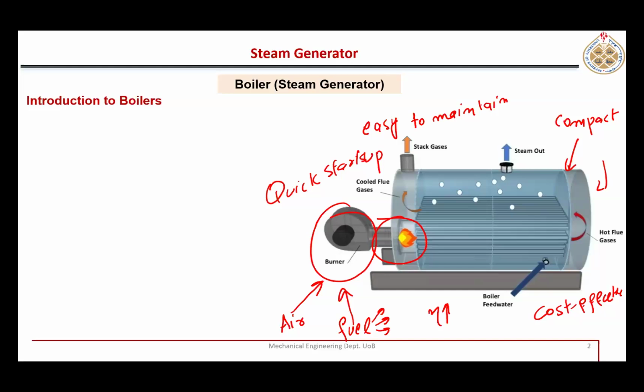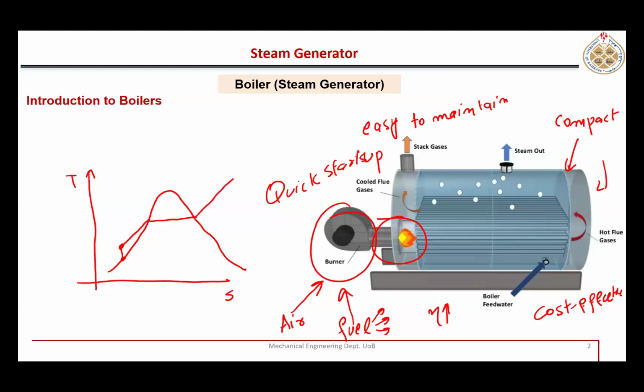One important thing in steam power plant, we already used this T-s diagram to present the boiling process. If you remember, it was after the pump. Now this was the process in which heat is applied to that water to convert it into steam. But specifically, the term boiler is only used for this portion inside the dome.